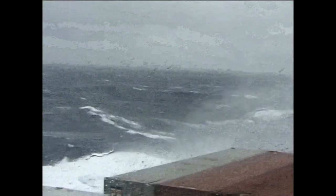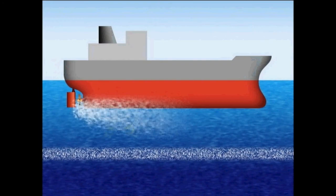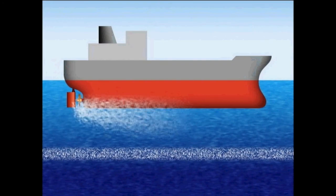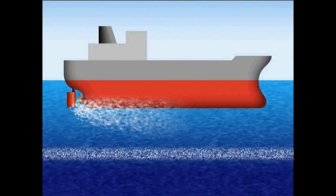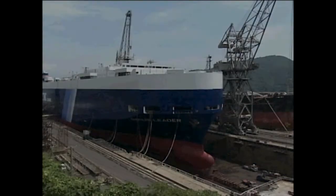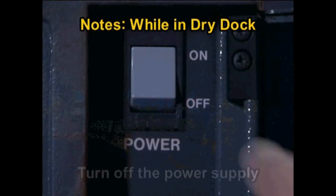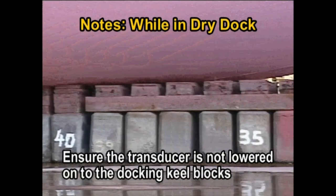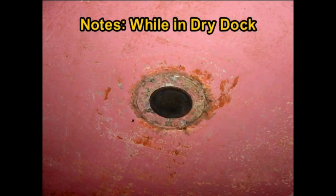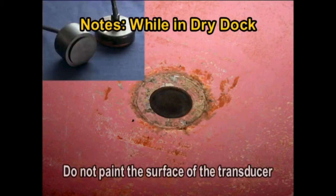Due to its nature, however, Doppler sonar speed log accuracy is susceptible to waves during rough weather and bubbles generated when the ship goes astern. Moreover, speed error can be caused by noise interference, etc. Precautions to be taken when in dry dock include turning off the power supply, ensuring the transducer is not lowered onto the docking keel blocks, removing crustaceans, etc., adhering to the surface of the transducer, ensuring that the surface of the transducer is not painted.